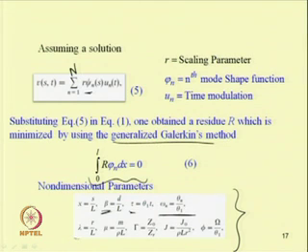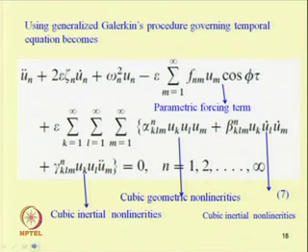Lambda is the non-dimensional scaling parameter, mu is the mass ratio, mu equal to m by rho L. The non-dimensional forcing amplitude is Z0 by ZR. Similarly, J equal to J0 by rho L R square, and the non-dimensional external frequency phi equal to omega by theta 1, where this theta 1 and other terms. After writing this and applying the Galerkin method, the equation reduces to this form.